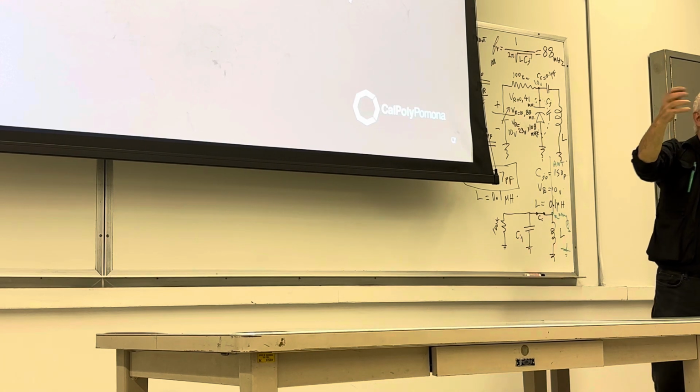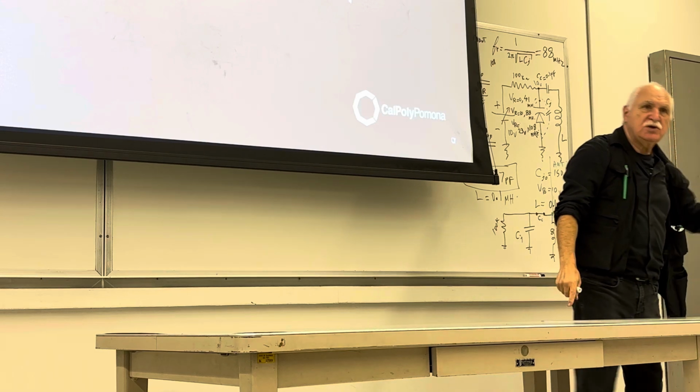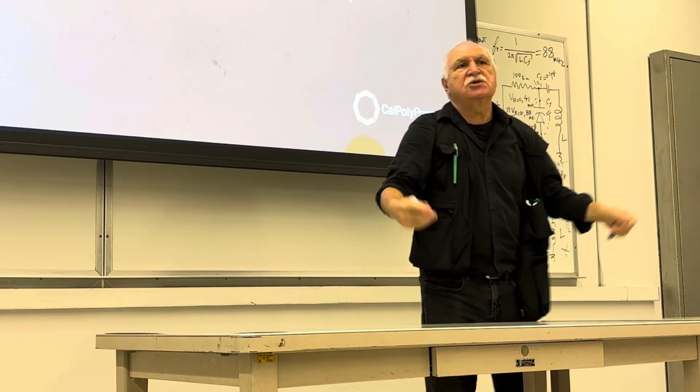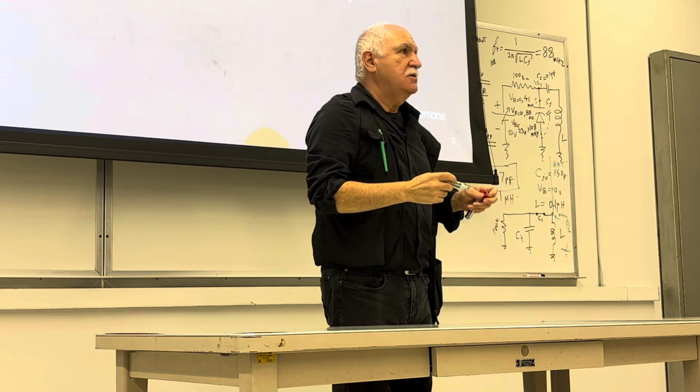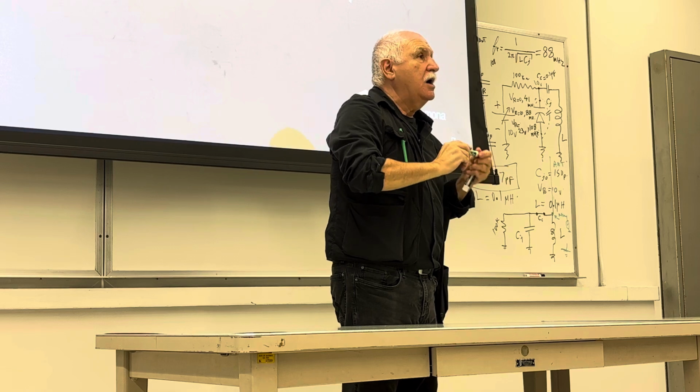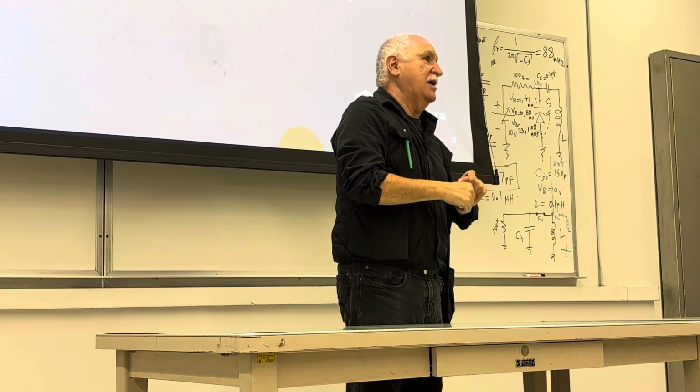Because those buttons, they bring from the memory the code corresponding to exactly that analog voltage that produces that capacitance, that produces that resonant frequency where the desired station is. So that's the principle. That's the application of this diode. Now imagine how much application that is.